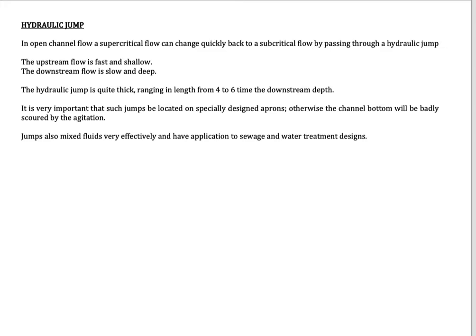Okay, and then the relation of that one, the supercritical, critical condition, and subcritical, is actually about one phenomenon called the hydraulic jump. In open channel flow, a supercritical flow can change quickly back to a subcritical flow by passing through a hydraulic jump. The upstream flow is fast and shallow. The downstream flow is slow and deep.